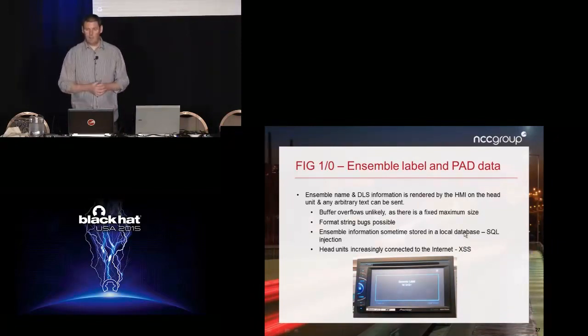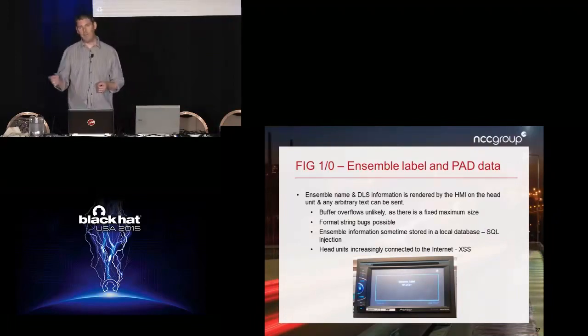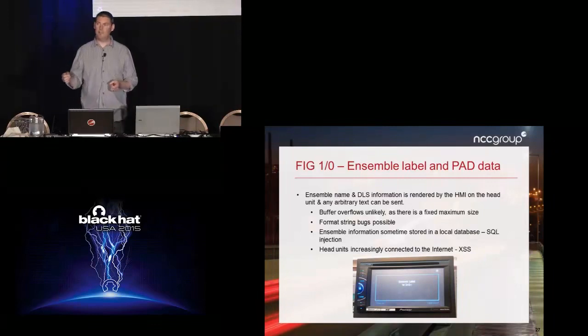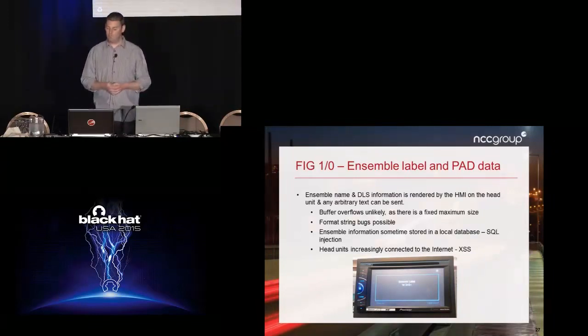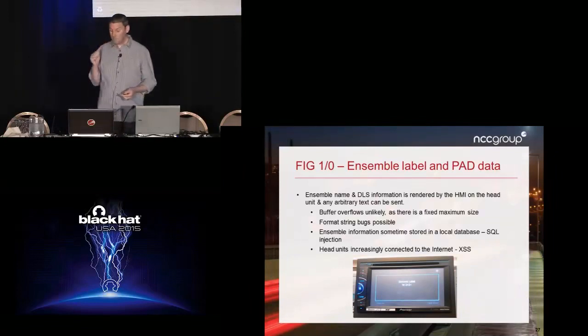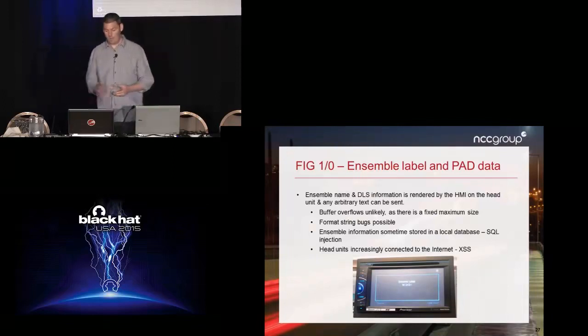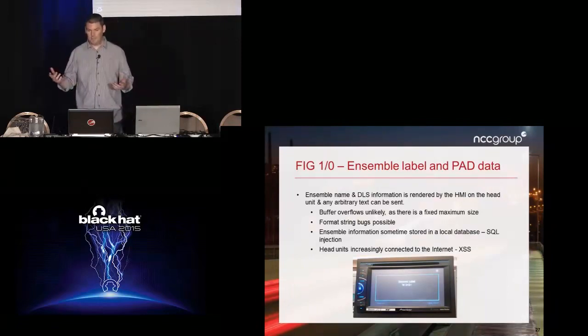A lot of the head units we've looked at implement SQLite. So there's the potential of SQL injection in some scenarios. Certainly if the head unit is storing the list of the radio stations, the DAB stations and ensemble names that you've tuned to, so if they're getting stored off in a database and you provide a label which contains SQL, there's the possibility of SQL injection that way. And I mentioned the fact that some of the head units are connected to the internet, so there's the possibility of cross-site scripting.